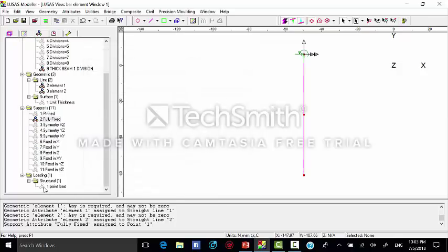So you can see that the point load is not active. In order to make it active, you have to select this point with your mouse and drag and drop. You can see that this blue color represents the load applied at node number 3 at the bottom. So now we have completed the modeling task, and we can run the problem by clicking this yellow button here, solve now.